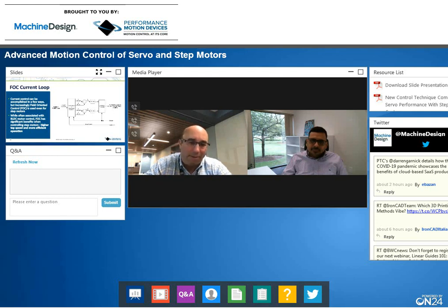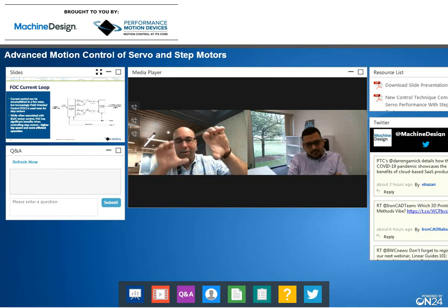And then you put the FOC piece on top of that, and really, with all the mystery of FOC, when you distill it down into some simple things for people who aren't familiar with it, there's these two terms they call the D and the Q term, and those are magical terms, but in reality, they're kind of a simple concept. The D term is this thing called the direct term. It's when you have a coil around some steel and you have a tooth, and you turn the coil on and the magnet wants to line up with the tooth. And that's a direct pull. And that's what the D term is.